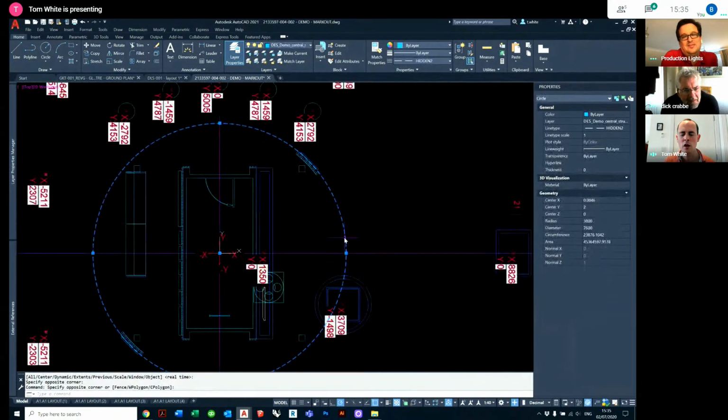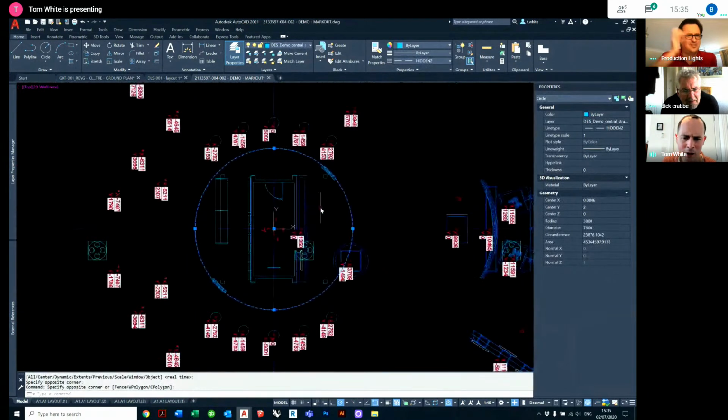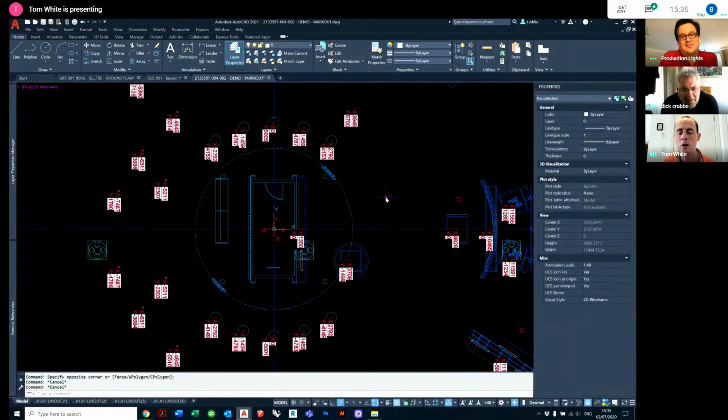Another visual way that you might see is this circle here. It's deemed as a circle, but you might be zooming in and out so many times, and you zoom in and you're like, hang on a minute, isn't that faceted or very, very heavily faceted? And that is the computer just thinking, I don't want to focus on the whole drawing because the user is using the whole drawing. Some of the things that I can simplify visually, I'm going to simplify: arcs get faceted, circles get faceted. So one way to overcome it, you just type in regen, and like Dom said, it goes over the whole drawing, regenerates everything, turns arcs visually back into arcs and circles visually back into circles.